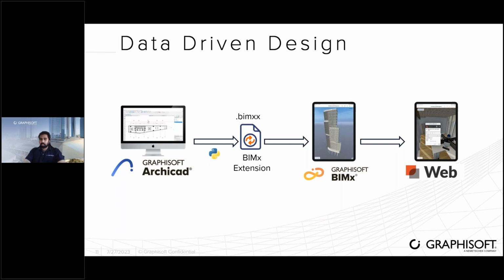There is a lot of information that we have captured inside dRofus, right? We can access that information from the BIMx interface using the dRofus web. So we have generated this Python script which will auto generate the BIMx extension for me from the Archicad model. Whatever the components are linked with dRofus, it should be able to find those components, or work based on the selection that we do, and then it will generate this BIMx extension, meaning it's auto generated. You're not creating the BIMx extension manually.